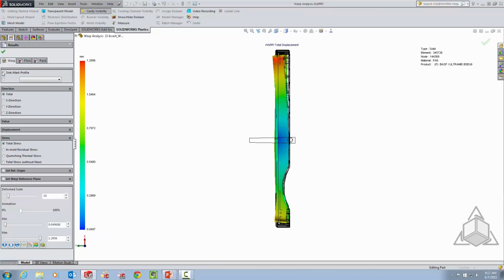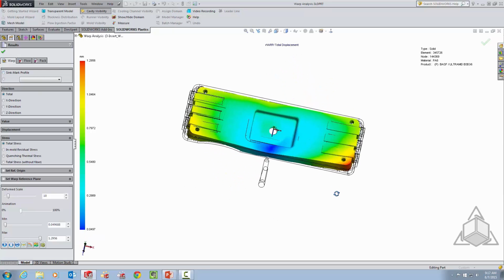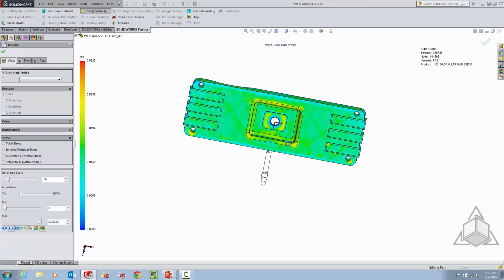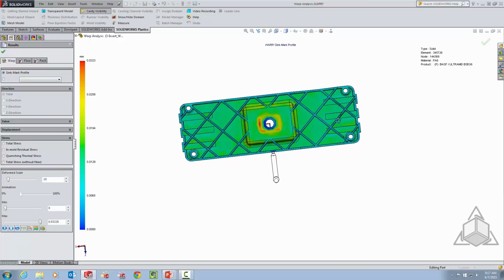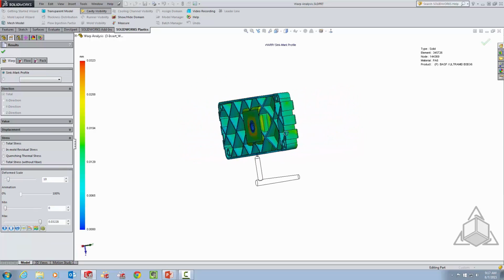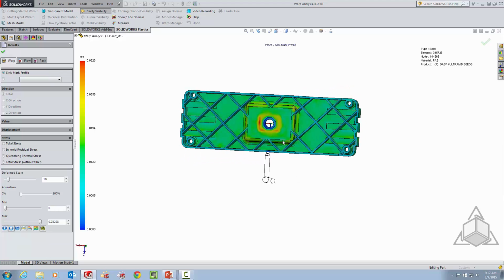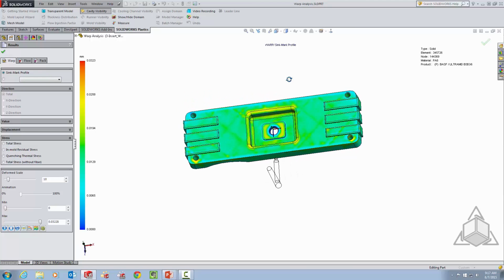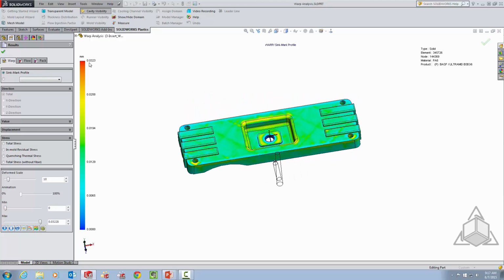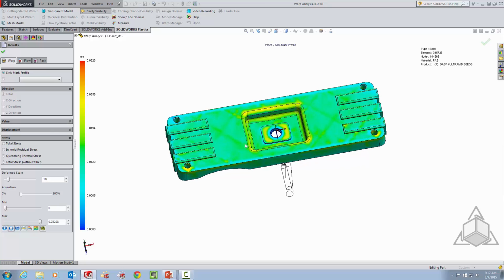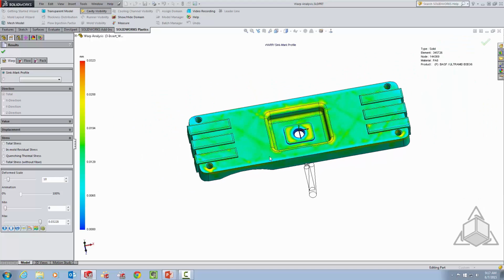And so we'll start off by looking at our sink mark profile. So when I select sink mark profile, you can actually see all the sink marks that are present in the part. So there's quite a bit of ribs on the back here, but in terms of displacement, 0.03 millimeters, so it's not that much. We could get away with it, and again, this gives you much better results in comparison to the flow analysis portion.